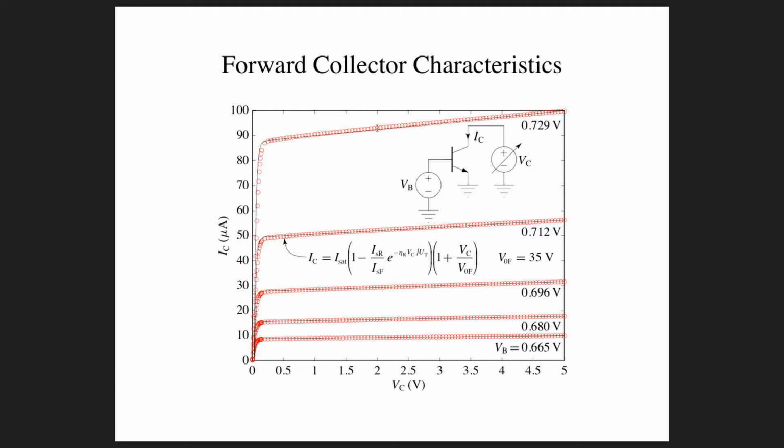Okay, by contrast, here we're changing the collector to emitter voltage by 5 volts, and here we're getting a 10% change in the current. That means we're multiplying the current by 1.1. And that's a very, very different kind of proposition than multiplying the current by a factor of 10, which would be a 1,000% increase.